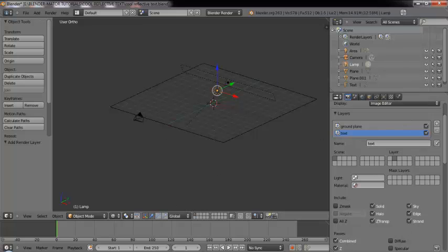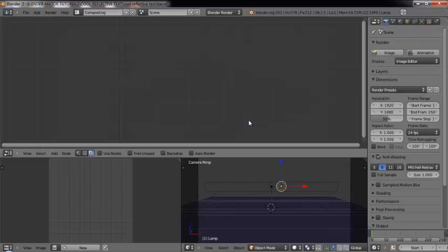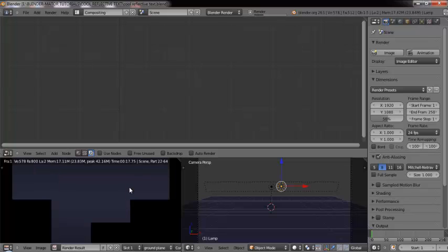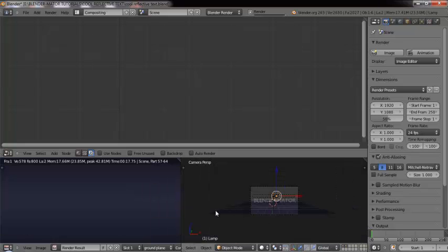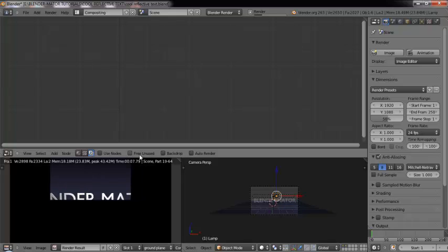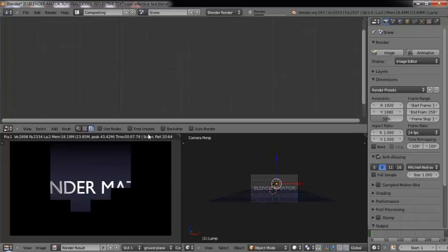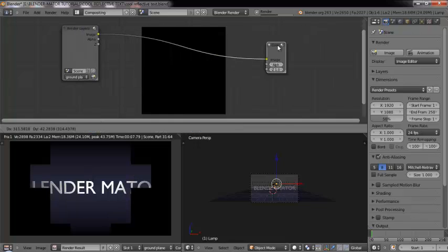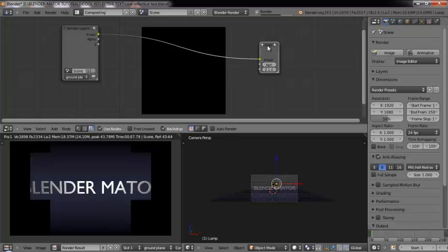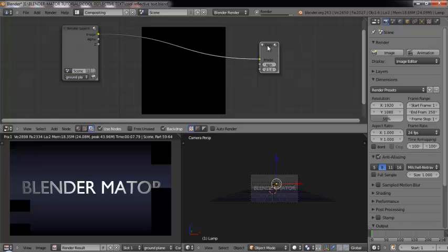And basically there are no changes made to the render settings. So we have basically two render layers. Fine. Now going into the composite mode, I need to render both the layers. Take a basic render and then go into the compositing node. I'm going to just basically add some few compositing nodes, nothing fancy or very complex, just to enhance the effect, the glow and things like that.